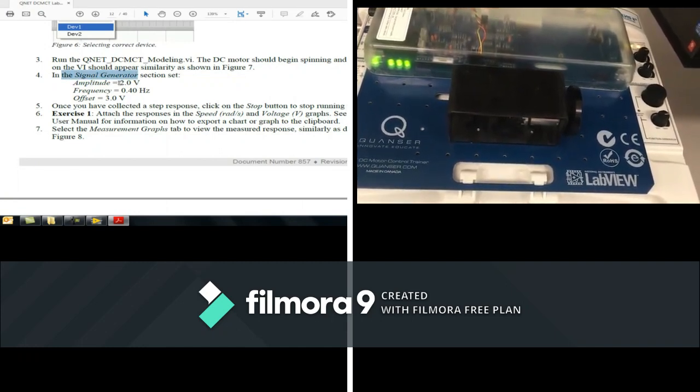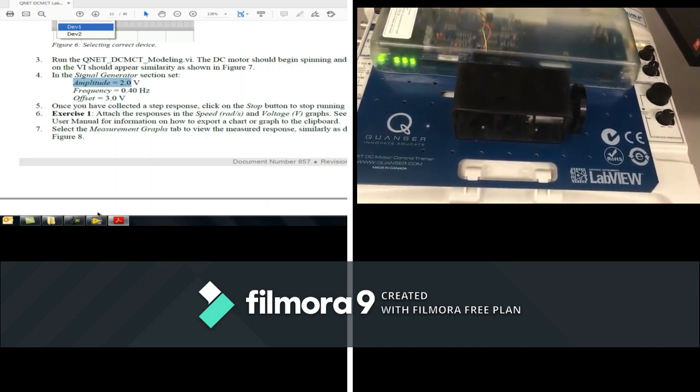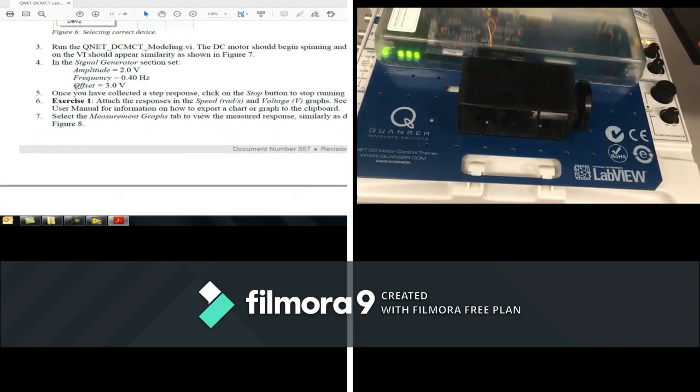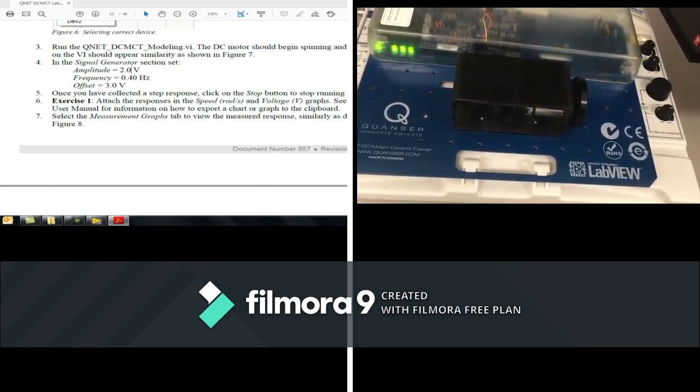Good. So now if you want to start, we have the instruction to put the amplitude at a specific value: amplitude 2 volts, frequency 0.4 and offset 3. Good. So what else?